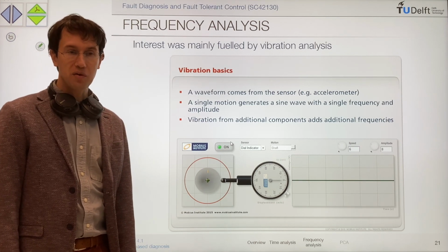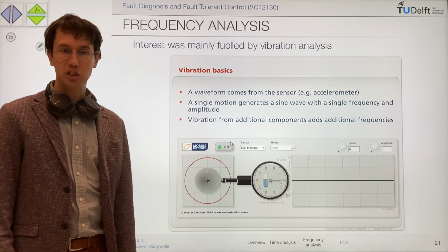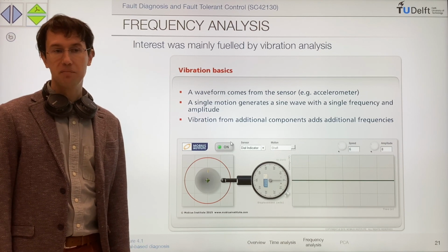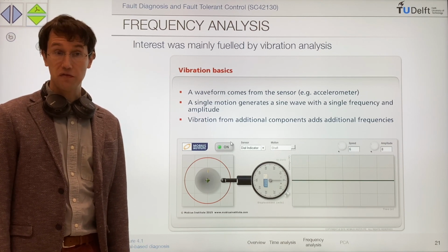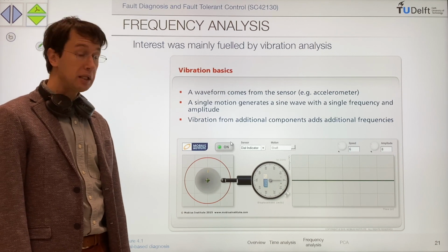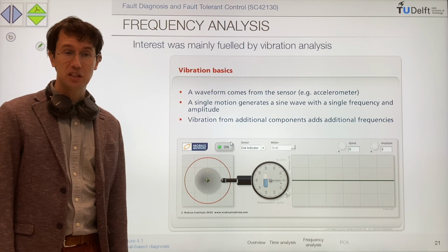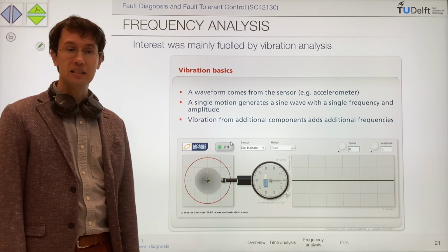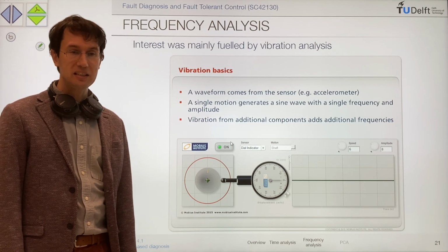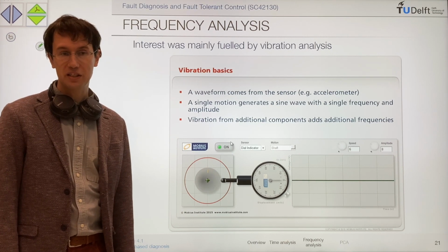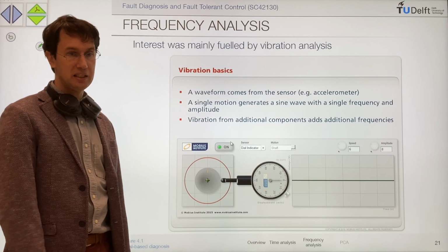And if you see components that are not matching those harmonics that you expect, they can be an indication of physical damage. Because indeed, when you have a rotating machine, an axle that is damaged is introducing some higher frequency components, as we can see in this example.